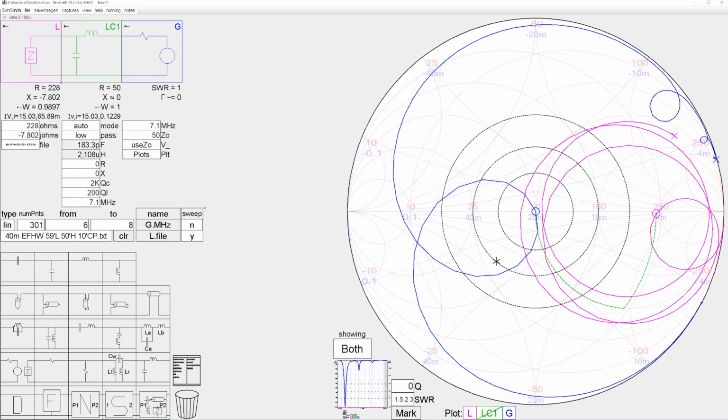You can try doing an unun with an end-fed half wave. If you've got an end-fed half wave and you scan it with your NanoVNA, capture the S1P file, import it into your PC, drag and drop it into SimSmith, and try your auto tuner, try L and C network combinations, and try using an unun at different frequencies and see what you get.